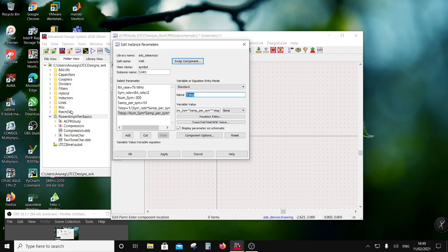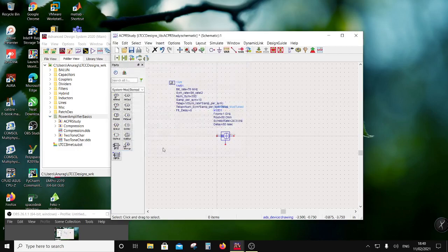So I am going to say that the filter delay basically is at least half the filter length. Okay, so let's say the filter length is 16, so then the filter delay is, let's say, 8, right? So 8 symbols. Okay, so I'm going to put here FLT delay, and that I am putting as 8. Okay, so I guess I have everything in place here.